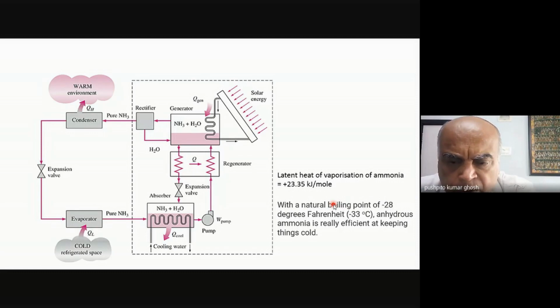By the way, I think it's important also that we understand that with the Joule-Thomson effect, we are really talking about the fundamental molecular level interactions in the gaseous state. So a compressed gas is expanded to make it liquid. But we also know that, for example, I can take a liquefied gas and I can vaporize it, in which case I will actually require the latent heat of vaporization. If I do it under adiabatic conditions, then part of my liquid may expand.